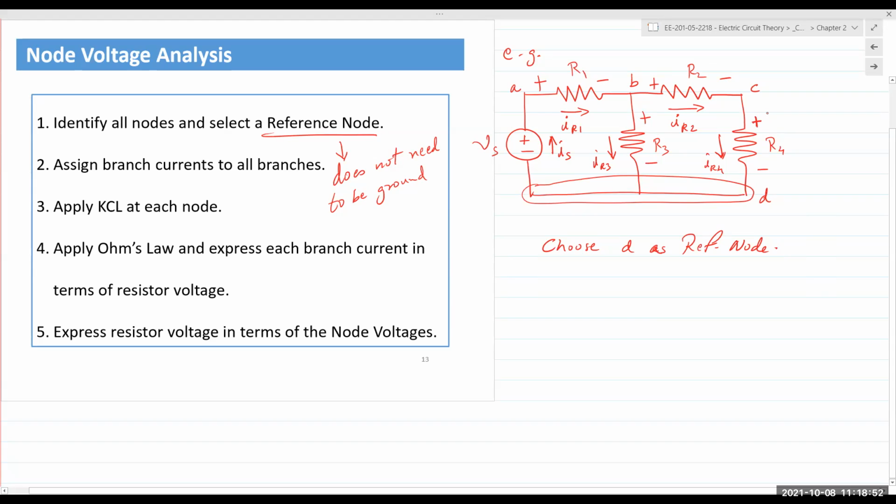This cannot be an illogical assumption, meaning if the arrow is going from left to right, the left end will always have to be plus. You cannot choose current going towards the right and then put a plus over here. It has to be on the left. Okay. And that completes the setup of the problem. This is what is expected of you. Actually, the arrow should be the other way around.